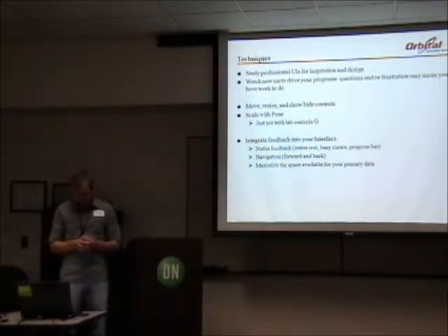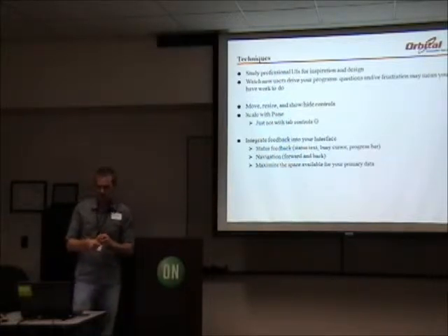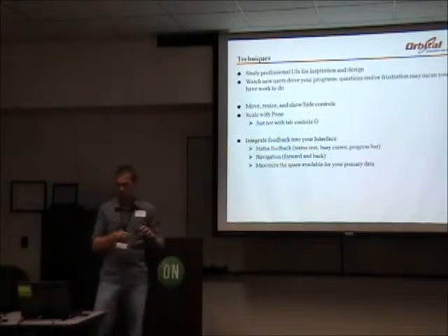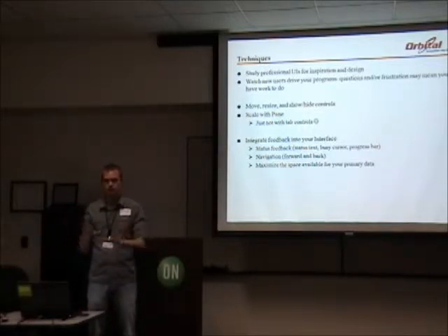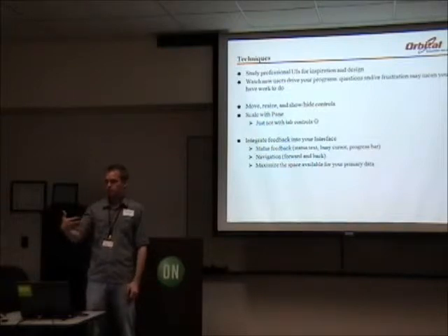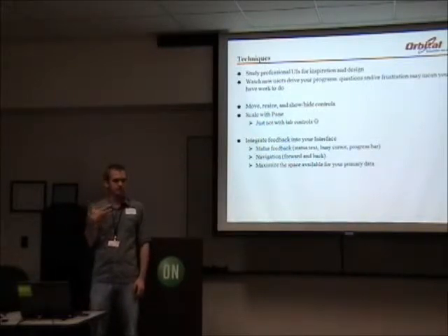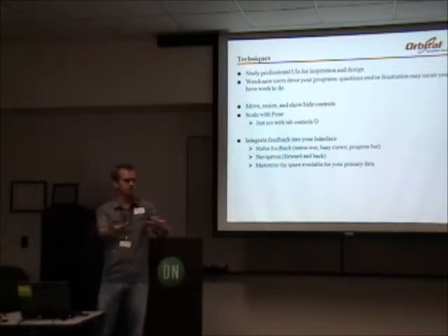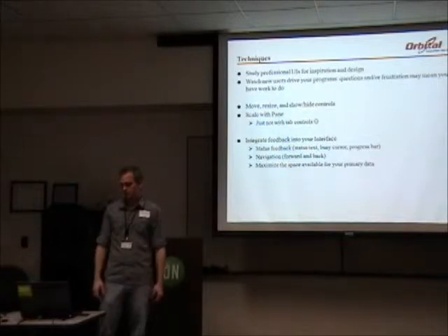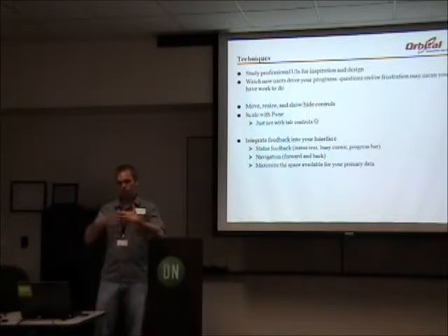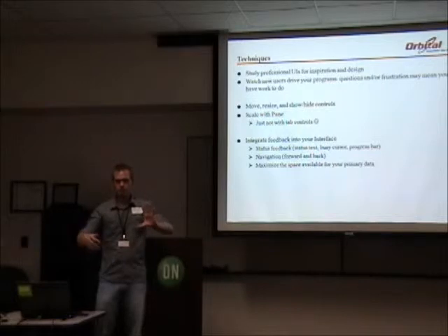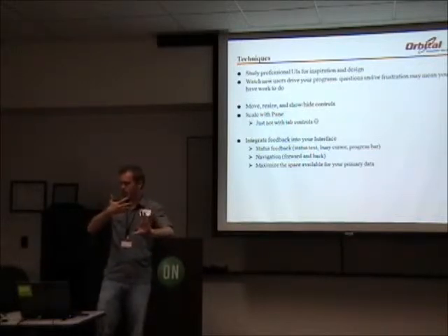3. We talked about resizability a little bit, but I think there's a power in LabVIEW that we don't use quite as much as we could, which is to move and resize and show and hide controls on the fly. We've got property node hooks for all of these things. We tend to think of the user interface as static. You design it once, it lands there, it's kind of where it lives for life. But a lot of the power we don't use is to resize things. Or you've got more than one thing that can take that main data space on a display. Well, you hide 2 of the 3, and you show the one that you want in a given context.